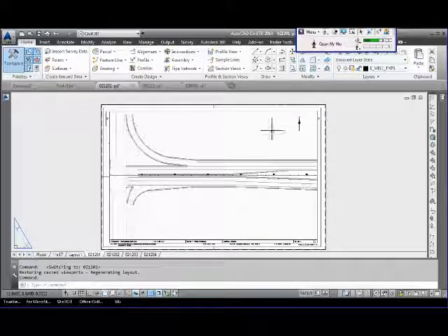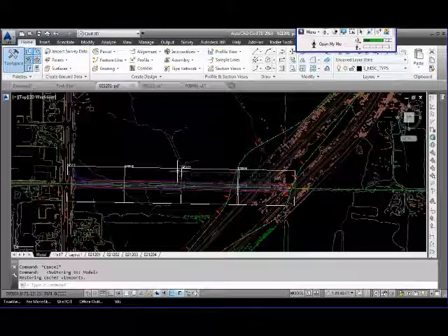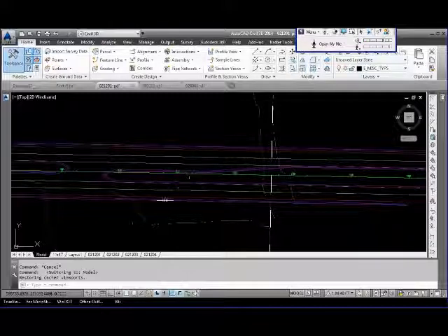You could set up layer filters for your use and filter out the layers that you use the most, and then you really don't have to open that very often unless you're messing with plot styles and all sorts of stuff like that. So having items open a lot can slow you down, and it's something that you can manage as a user, and that's not necessarily system generated.